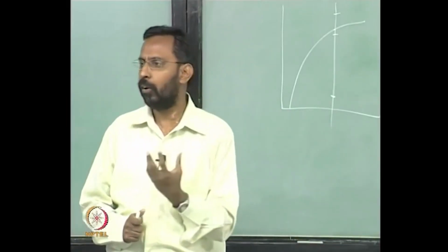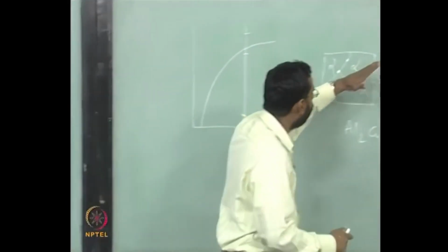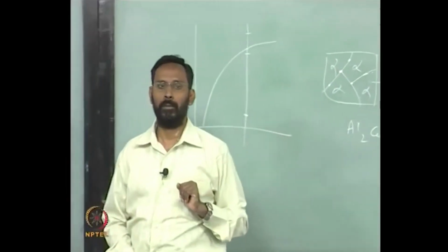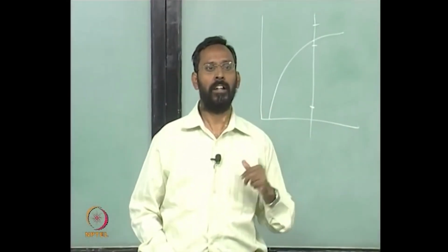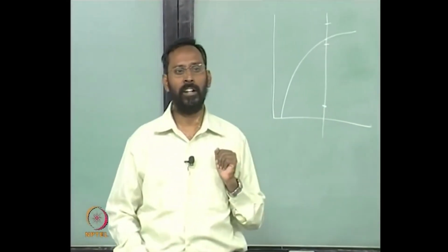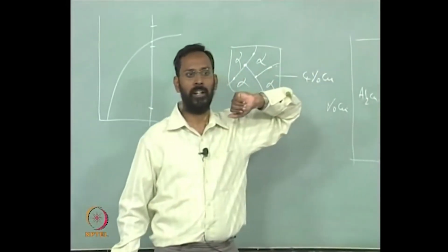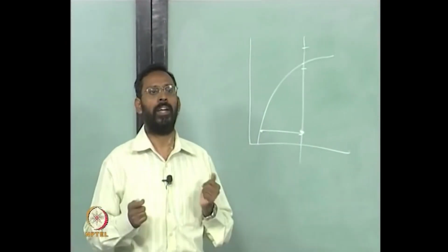So the need for coherent nucleation comes into the picture because of the difficulty in nucleation at the grain boundaries and the necessity for nucleating within the grain. And the moment there is a necessity for nucleation, where is the necessity coming from? Because it is supersaturated. It cannot remain as alpha anymore. Once you bring it to that temperature, this much supersaturation is not allowed. So it wants to give away copper atoms.